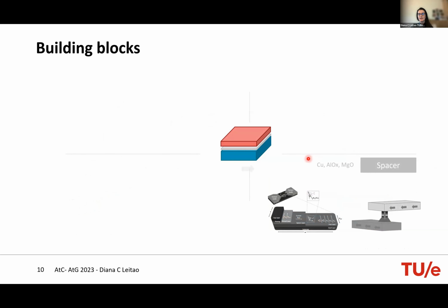So this brings us, in a very simple picture, to the key role of the spacer layer. In setting what type of magnetoresistive device we are going to design, an all-metallic one or one with a tunnel barrier, the truth is neither of these materials can be seen without the ferromagnetic electrodes, be it the sensing layer or the reference layer.